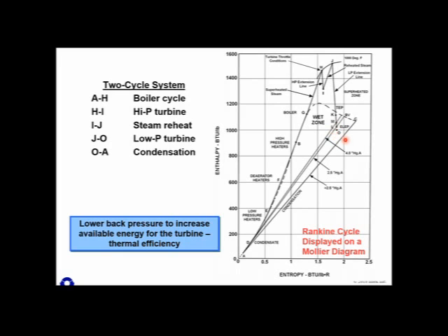And so keeping that condenser pressure low is a focus to increase the performance of electricity generation. So then that steam enters the condenser and goes through a phase change. We condense that steam down to liquid phase, and a lot of that energy is waste heat out the cooling water. And so then the steam returns to its liquid state at the bottom of the hot well. So that's how condenser pressure affects power generation.